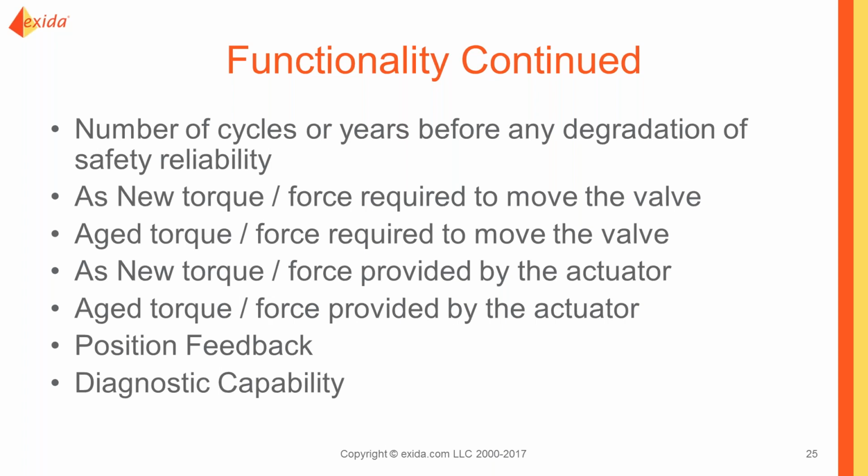So that's a key thing to understand: that the actuator valve combination, that the actuator is going to be able to provide the necessary forces to move the valve when needed, but not such high forces as to damage the stem or plug by over torquing it. So that's an area that we're seeing more effort on in general in the market, and that there still needs to be quite a bit of work to do. Again, if you're going to be using diagnostics, you're going to want to consider position feedback and or diagnostic capability at the design level.